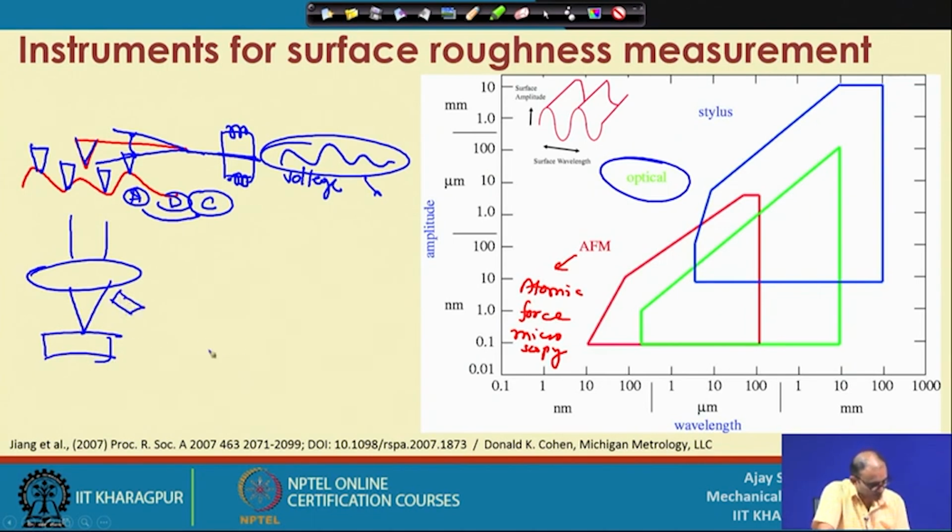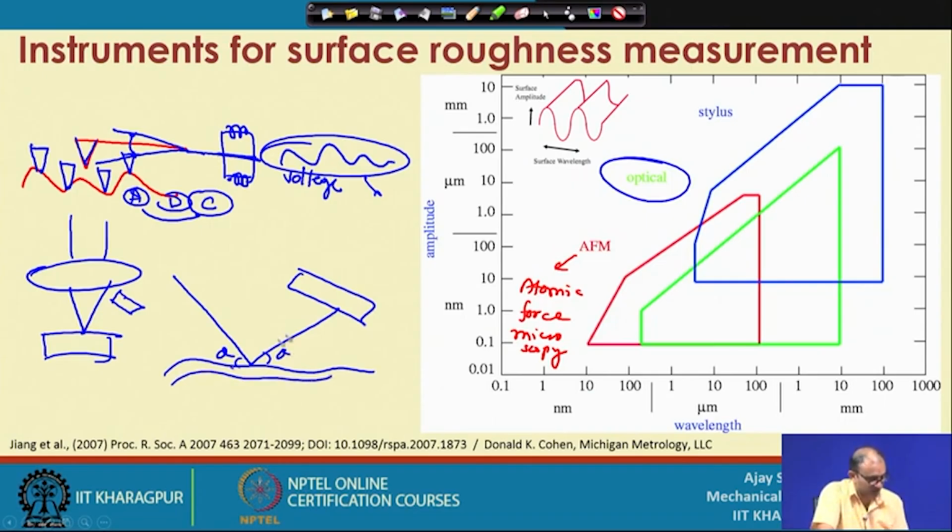So, what is going to happen is, suppose you have waviness and light is passing here, and you have one particular receiver. When you have a flat surface, this angle and these angles are the same, and if you have waviness here, then these angles are different. So this particular location will be different at different locations, and this way you can optically measure the roughness.